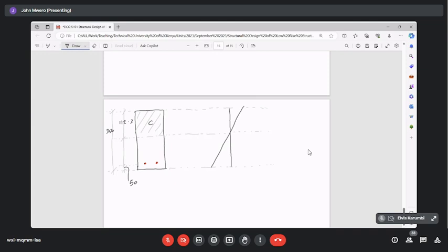So we can calculate this value from the neutral axis to the reinforcement, and it looks like 187.7. We have the concrete cover, and we have the depth of the neutral axis, so we can calculate this value of 187.7 from the total depth, which is 350. Now, we're coming back to this section here.